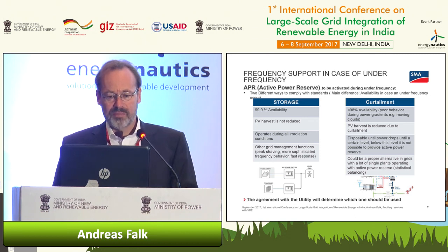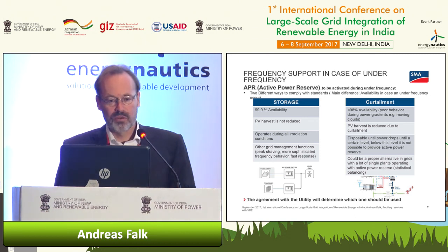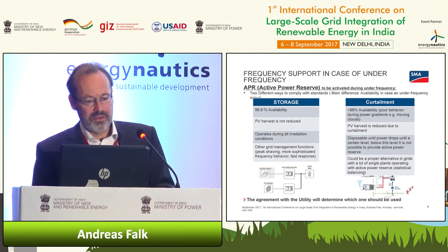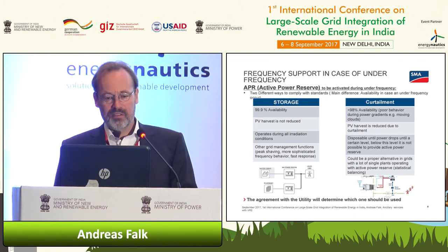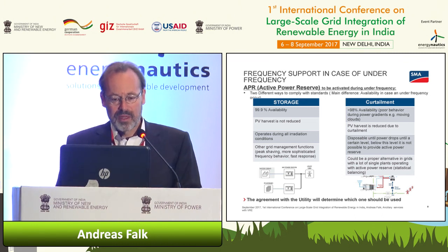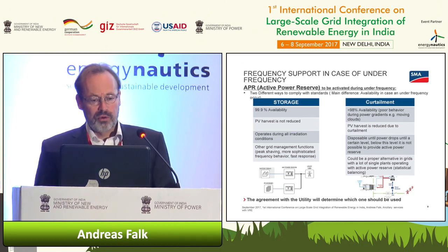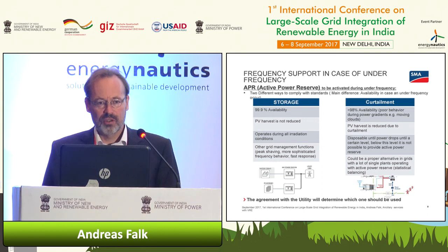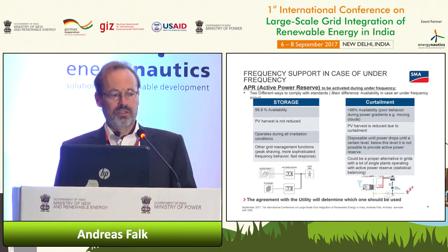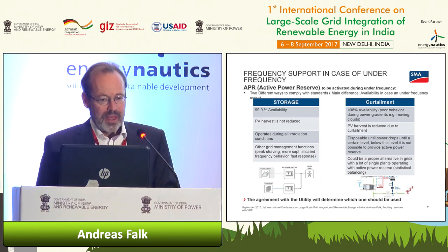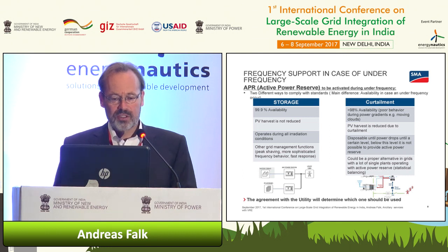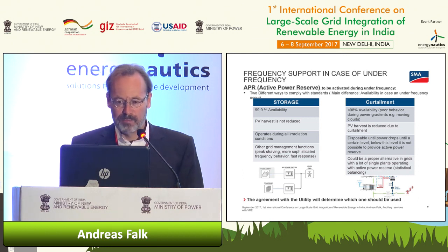in two manners. One is to install storages, and then you have a very high availability in a single plant. The PV harvest is not reduced. It operates during all irradiation conditions, especially also during the night. And other grid management functions are feasible in parallel.